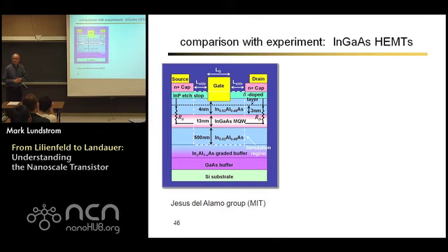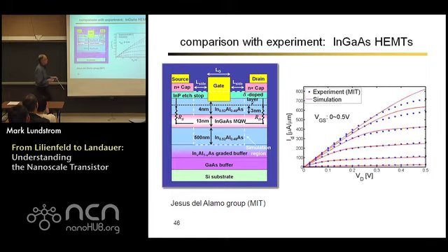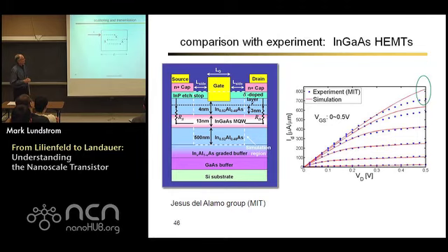There are transistors, however, that operate essentially at the ballistic limit. If you look at III-V transistors made on high mobility semiconductors, and you do the same kind of comparison between the ballistic theory and the measured characteristic, you can see that a transistor like that operates almost at the ballistic limit. You know, nothing like what a textbook would say it operates at. So these things can become very, very important.